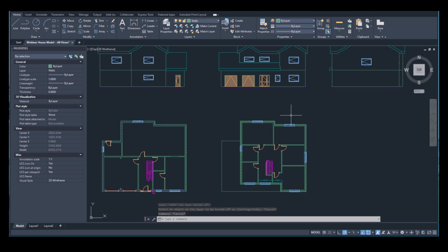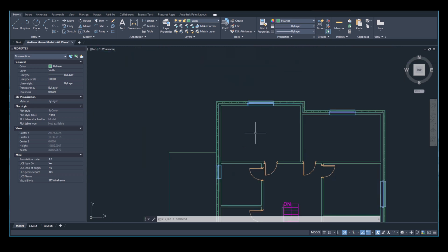The next thing I'd recommend is that we separate views or any view references into one file per view reference. The reason for this is that we can import only the references that we need, and we can also place them exactly where we need to when we're referencing the position of doors, windows, and other elements. So we can place our ground floor plan on the ground floor plan level inside of Revit, and then we can align the reference to that level, and we can place our elements accordingly.